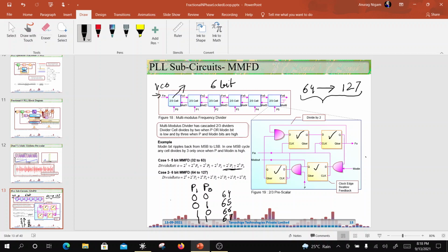One approach can be to involve something called current mode logic. The other approach is I cut down some blocks in here so as to speed up this cell. So we are going to take both the approaches. Here I am designing for Wi-Fi 6E, so my input is going from 3.8 gigahertz to 4.8 gigahertz. So my input to this divider is going to be this range.